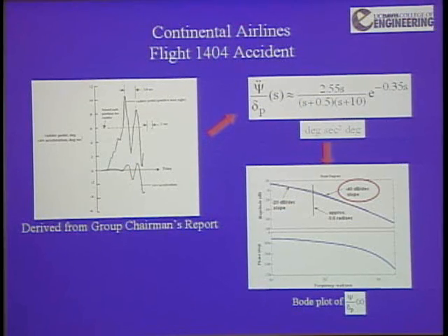So I did some real back of the envelope system identification, looked at a series of pulses that were going on with the rudder, matched them with the lateral acceleration, and came up with a model, the transfer function for the vehicle. Heading acceleration over pedal input, divided it by s squared to get heading over pilot input, and said, there's my system transfer function.